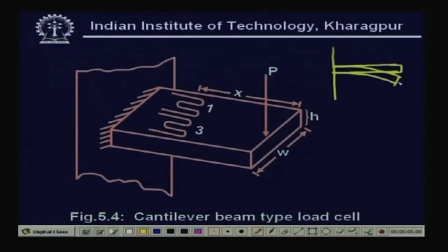But you see very carefully that the strain gauges are installed very close to the hinge point, here, and at the bottom also there are two strain gauges. The reason is stress is maximum at this point, not at that point. The stress gradient is also maximum at this point, so that is the reason we install the strain gauges in these directions.